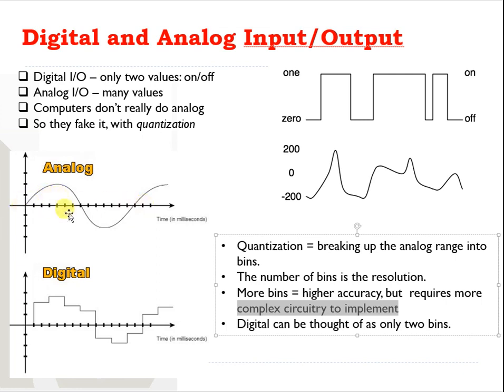Over time it is continuous, and here we have it in the quantized form. So you see that in this case we have a given number of bins, it's not only 2 bins. For a period of time, you see that in the analog form the value is changing, but in the digital form we have it constant. So depending on how much the analog signal changes, we will have a different value for the digitized form. We will discuss this again later in the course.